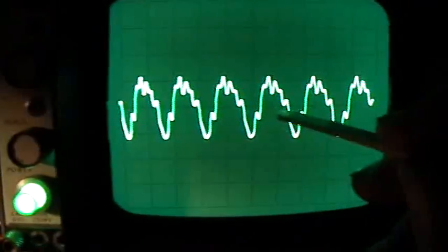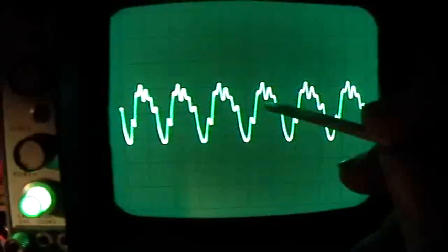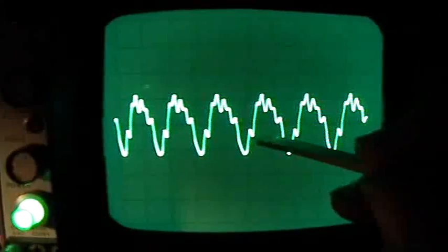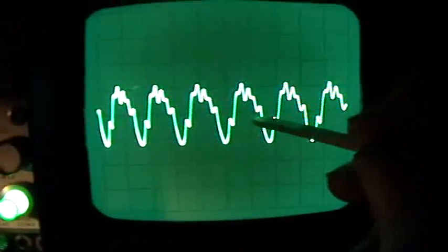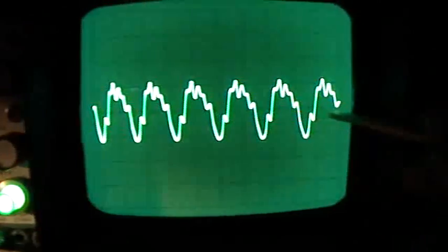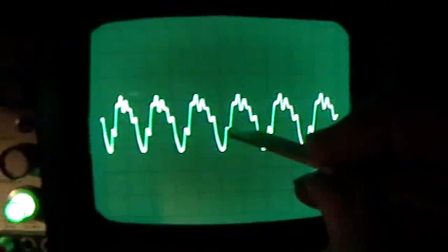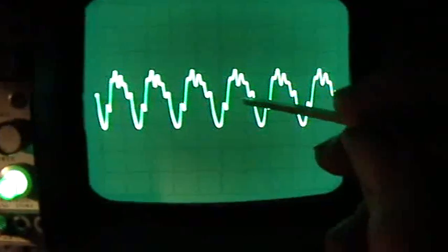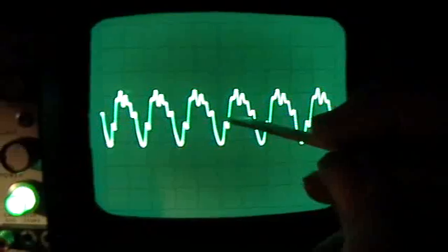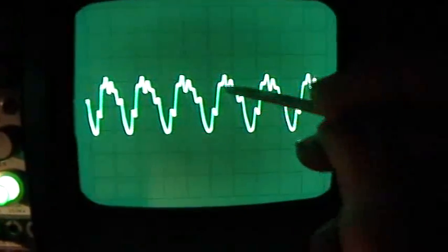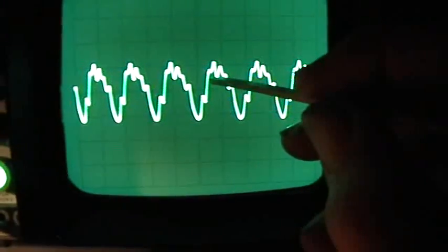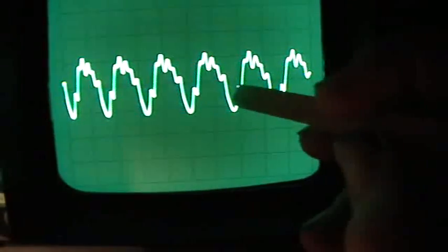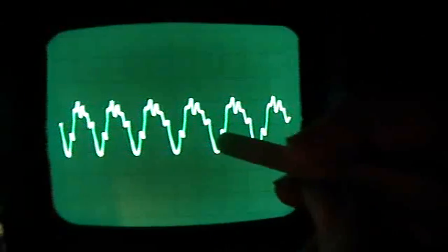And the areas of that instantaneous power trace, which is obtained by multiplying this trace by the instantaneous voltage trace, correspond to integrating over time, okay? And of course, if you integrate watts over time, the answer is in joules, or energy over that period of time. So you'll be interested in looking at the areas of the power that's going one direction compared to the areas of the power going in the other direction.